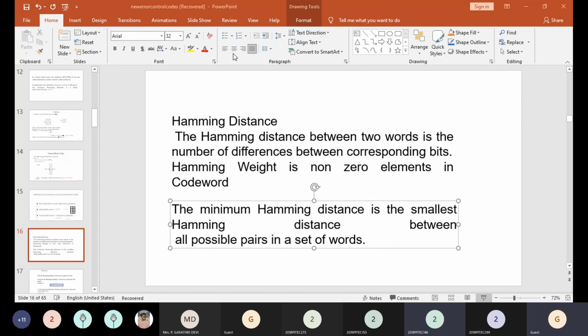A linear Hamming code is used to map 4-bit messages to 7-bit code words. The encoder mapping is linear. If message 0001 is mapped to the code word 0000111 and the message 0011 is mapped to the code word 1100110, then the message 0010 is mapped to what? So you need to find out what the possibilities are.